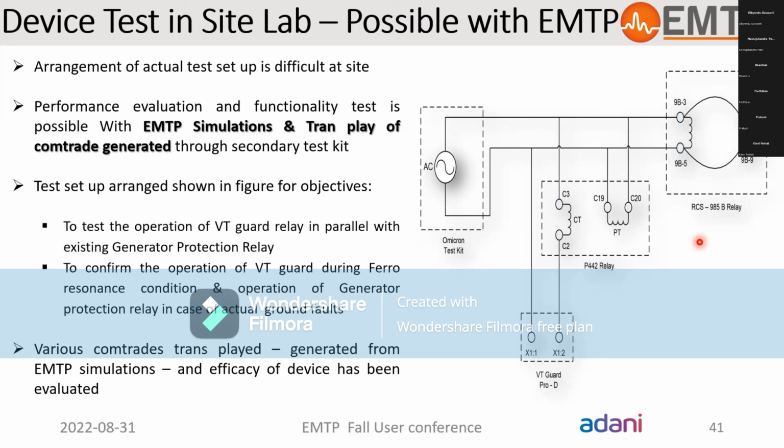It has been observed that if the three-phase voltages are balanced in nature, the zero sequence voltage appears across the VT guard terminal, the open delta winding. So no current will flow, and the device remains inactive and offers high impedance in the circuit. But as soon as the voltage across the VT guard increases above a certain value, it offers a low impedance path in the circuit and a ground path to the harmonics. In this way, it dissipates the oscillation energy generated by the resonance itself.